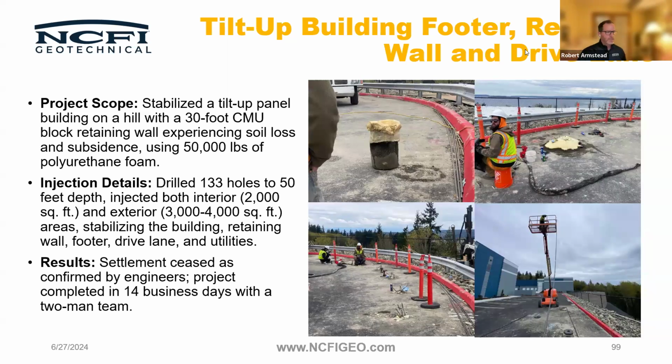What kind of soil types do you find that this is successful in, and what kind of soils would you find to be a challenge? Clay's always a challenge for everything. Deep injection with dual component foam works in clay, as long as you can get the clay to take it. We're not gonna permeate the clay particles with the chemical like we would in a sandy environment, or pea gravel, something like that.